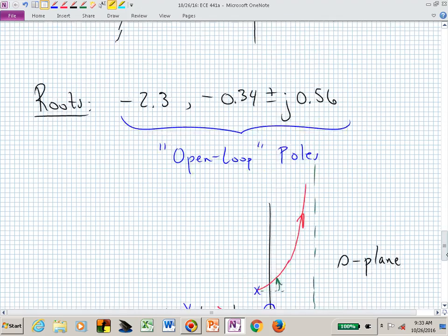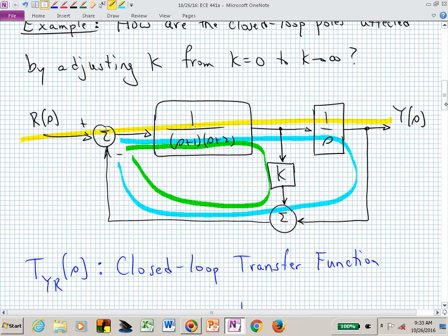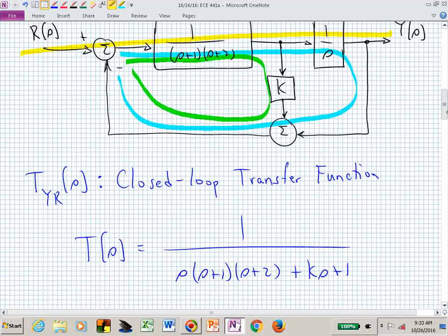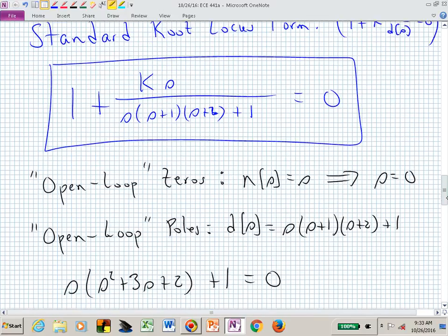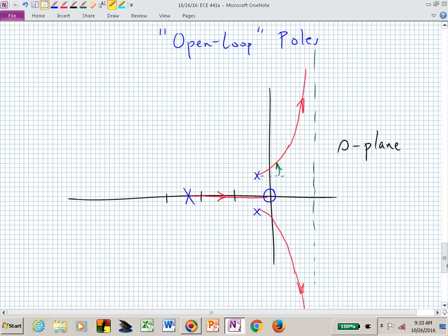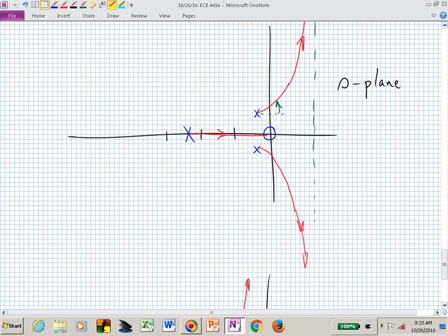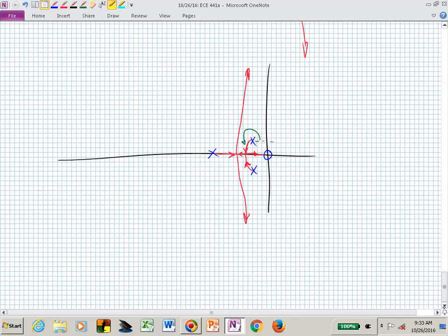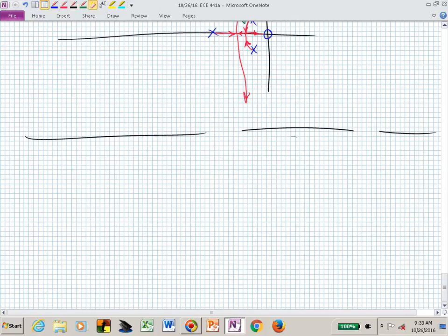So if the gain is 0, if k is 0 here, then in this case it's a little bit different, but in this standard form, we would be locked on those particular poles. So let's move on right now, because you've raised a good point, and we'll have to come back to that, but that's because the point being made, I think, is all hinging on that non-traditional pattern of the block diagram. So let's look at some of these rules so that we can understand which of these two patterns we might have in the complex S-plane, of those two possibilities.